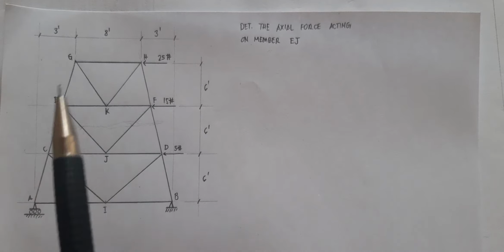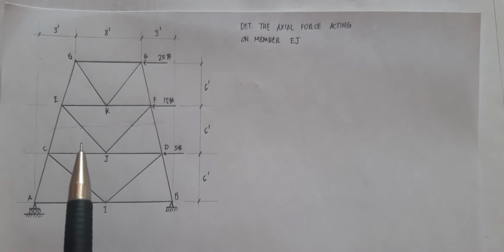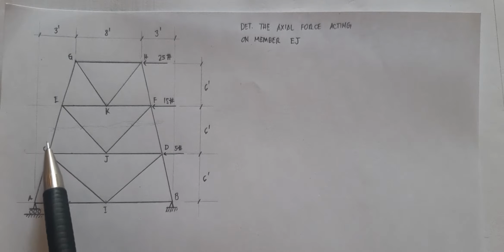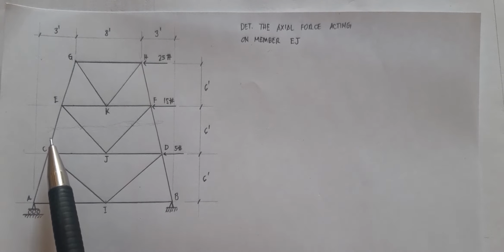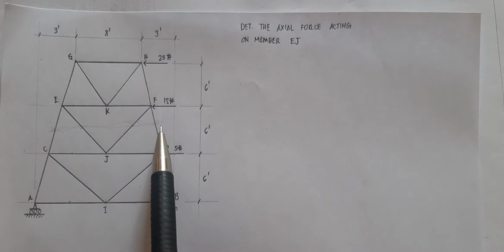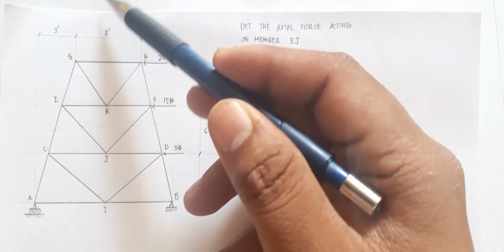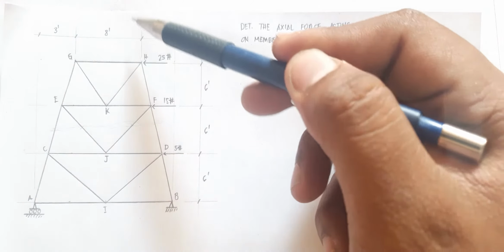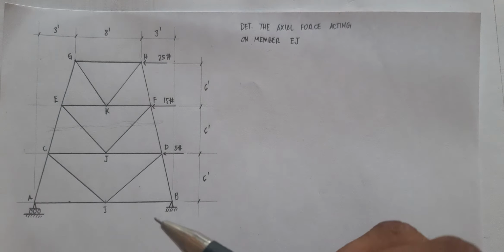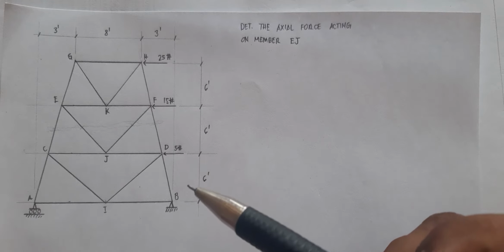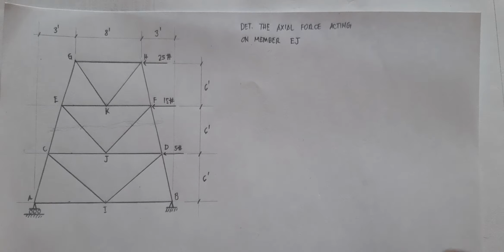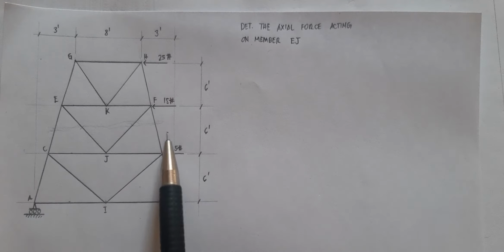Most likely, if you were to pass a section wherein one of the members is your required member, that particular section would be this section. Now you might be thinking you may project this line upward, then this one upward, this one upward, and the point of intersection somewhere above would be a point of moment. In that case you have two unknowns for that particular equation, and then you may proceed to the last remaining two equations, but of course you would still have an excess unknown.